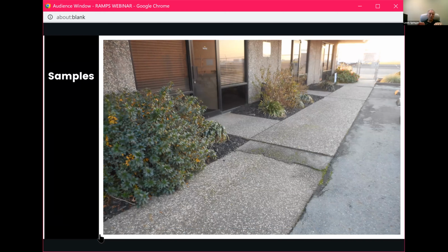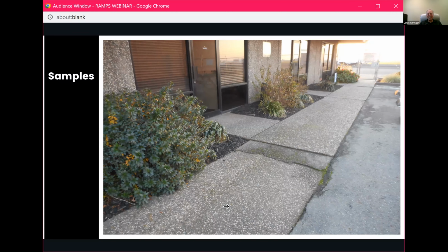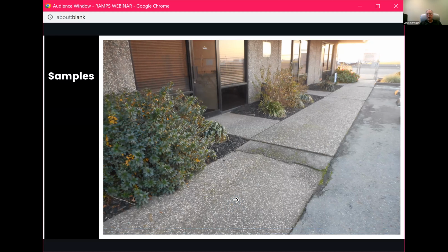But here again, this is actually the end of parking spaces. But it's because it's contiguous with the sidewalk, it now requires some kind of separation. So I actually designed a couple of different solutions to figure out which would be the better way to go, whether we separated it so it's not contiguous. If we added 3-foot detectable warning and then 3 foot of walkway,